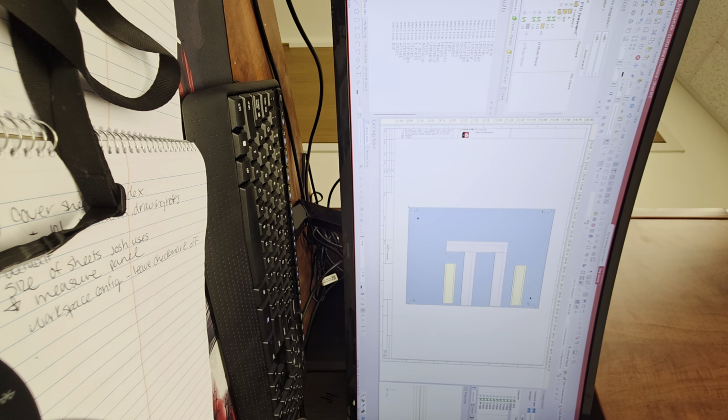Can we go through the folder thing again? How to organize them, just real quick? Sure. Okay, so we made this. We made the MP. Okay, so let's move these items where they actually should be, considering that's the thing about dynamic parts. When you bring in a dynamic part and you don't choose a location at the very beginning, they just go in this automatic folder. So for right now, let's collapse U2 and U4 for the time being. Looks like we missed the U4 on the selection. Right click on U4, just to ungray it out. Click device properties.